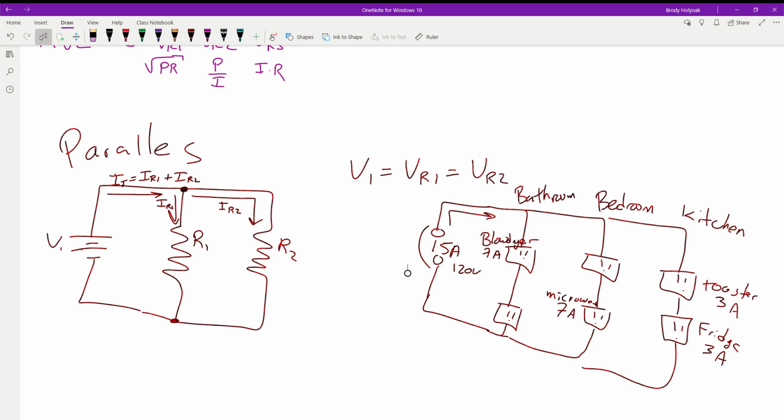Everything's coming through that one little device, and it could even be into a 20 amp line, but the box itself, the splitter, is only rated for 10 to 15 amps. So your circuit breaker is never going to trip because you never get over that threshold, but its internal rating is such that you're going to pull way too much current and melt it. That make sense? Parallel is very, very useful, but it's scary. Yes?